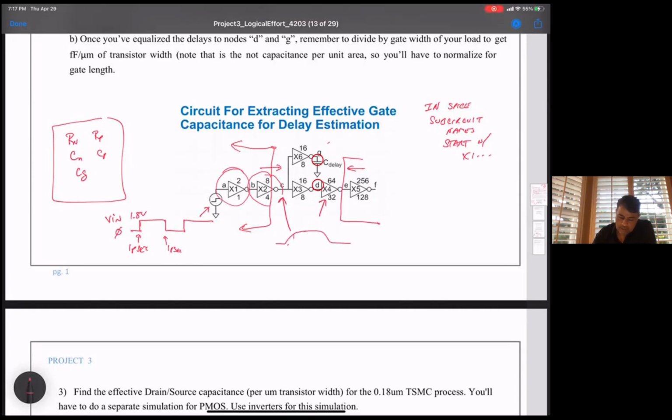So that's all these circuits are, these two first guys, that's all they're doing. They are giving you a realistic input to X3 and X6 here. And furthermore, this guy, X5, is making a realistic load on this X4. The reason is if you don't put any loading here, this X4's transition could be extremely fast and it could give you an overly optimistic or pessimistic input gate voltage.